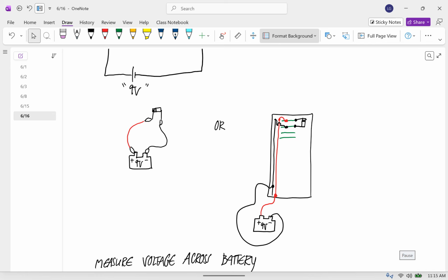And then you're going to insert the two leads of the multimeter to complete that circuit using the multimeter. Like when the train tracks break and Superman lies across it to complete the train tracks, that's what you're doing with the multimeter. Okay, so you make that break and then you fill it with the multimeter.